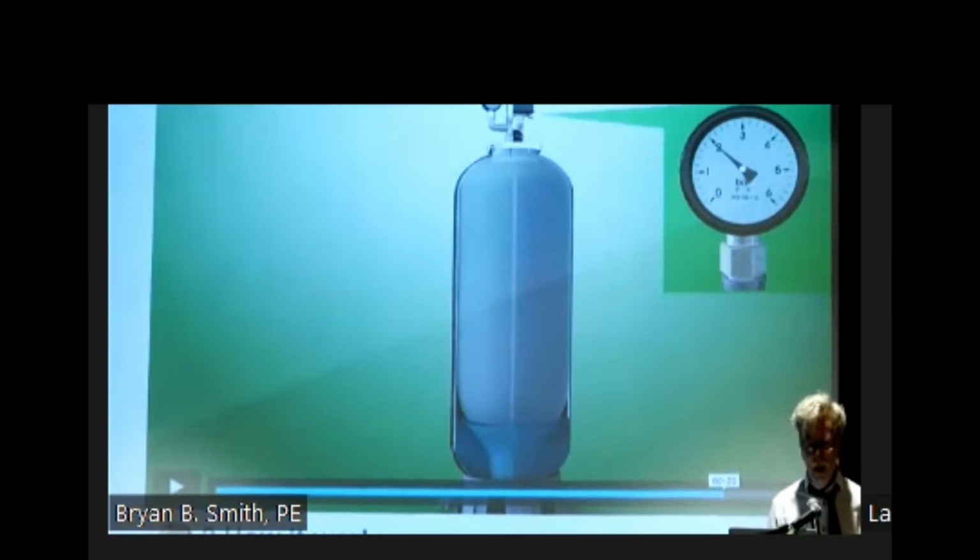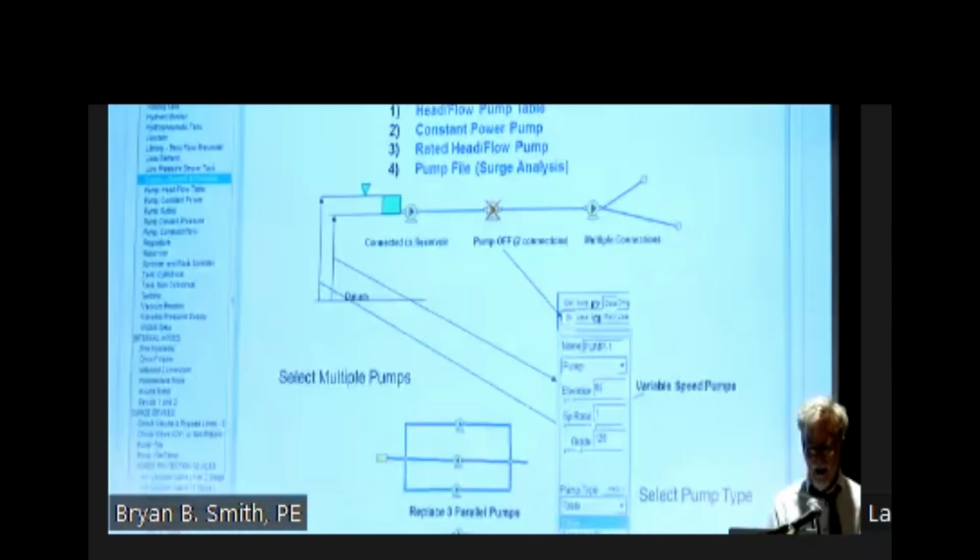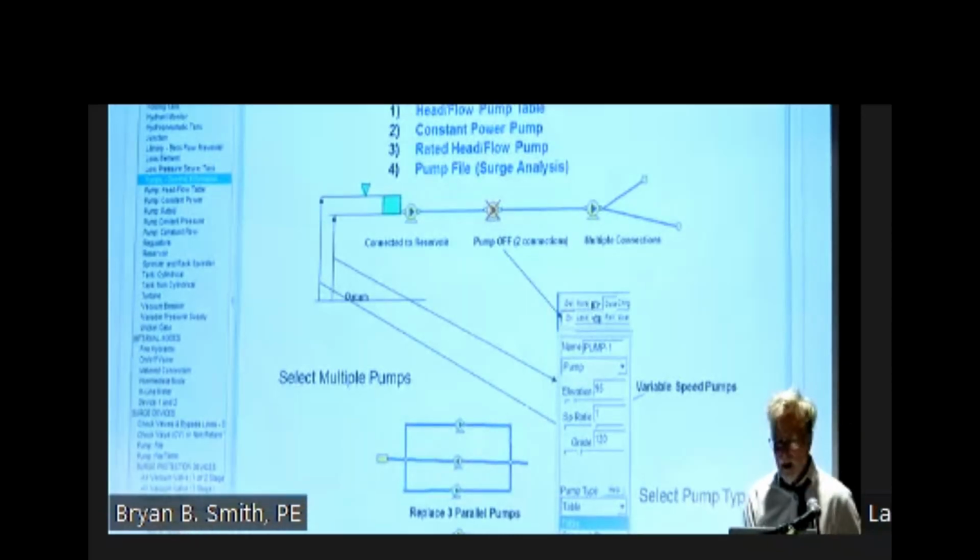So we look at the polytropic constant based on the length of the pipe and how quickly I need to give energy. So we're also calculating the polytropic constant within that gas for our piping system, depending on what's going on in the surge model itself.